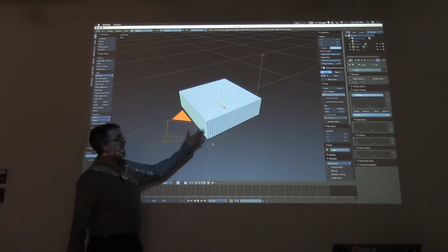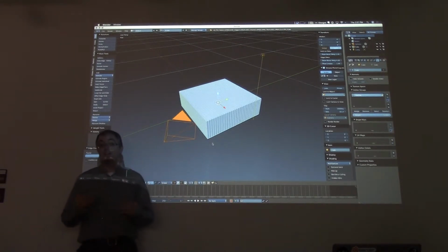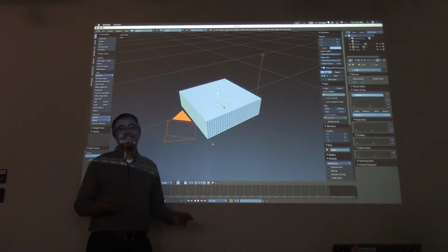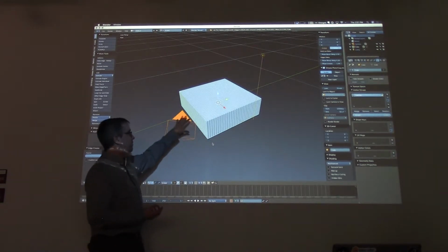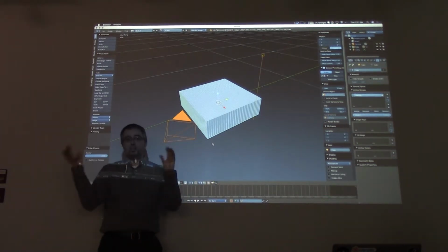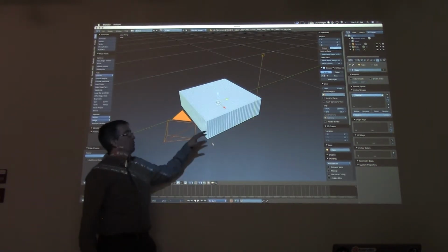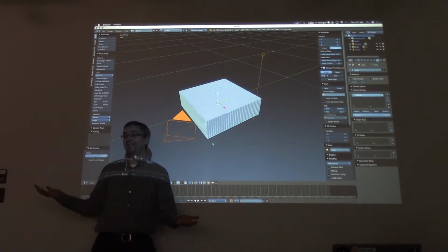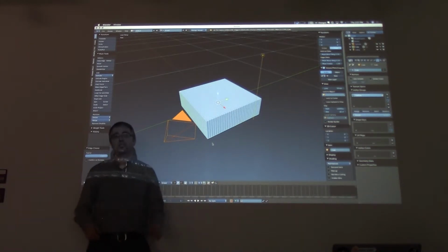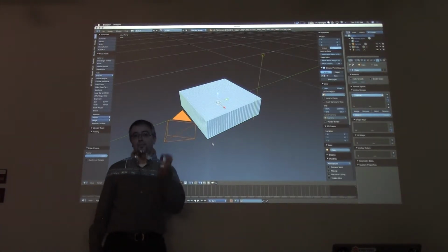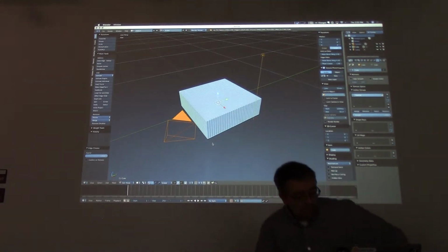Okay. So later on, we're going to be adding subdivisions, which is a way of adding more geometry without doing 100 loop cuts or whatever. But the subdivision plugin will naturally try and round everything off. That's what it does, it makes everything sort of cool and organic. Right. We actually want this to retain the feel of a block of wood, not a rounded thing. So we sharpened all the edges to tell the computer, hey, I know we're telling you to subdivide, but don't round all of this off. Cool? Yeah. All right, so we've sharpened the edges.